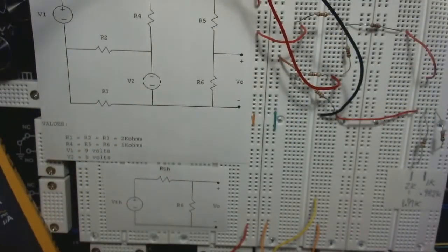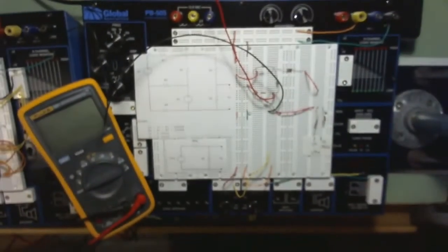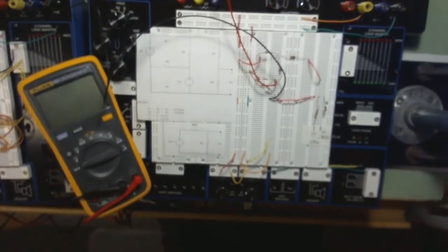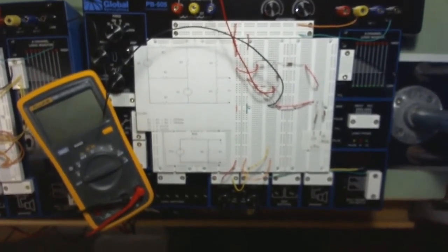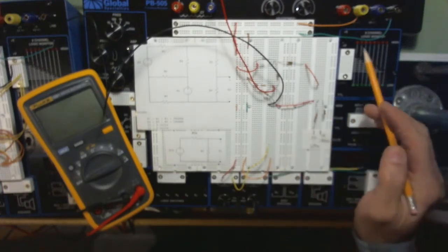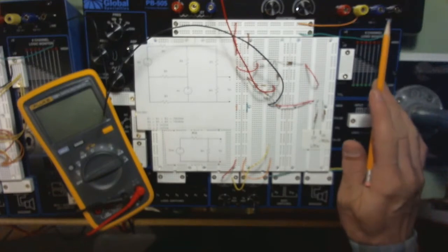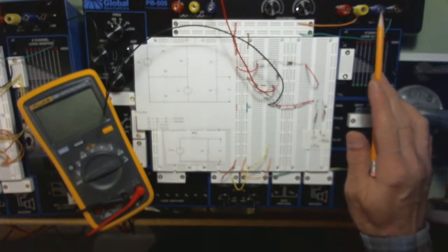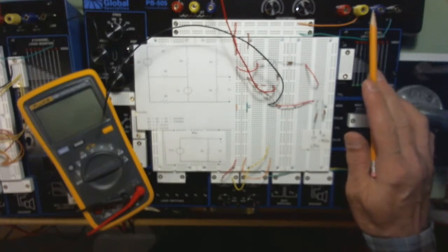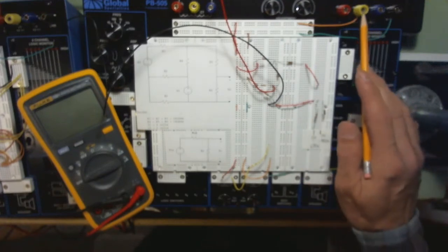I'll set this out of the way here, and I'm going to move the camera right here. It's probably going to be a little far away to really see everything, but I wanted to give you a little better idea of what's going on. Again, my trainer has a ground here. That's a ground lug. It's black, so it's a little hard to see on the black background. And then it's got a minus voltage, which we'll be using next time for our op-amp experiment. It's got a positive voltage, and that's what I'm going to tune to 9 volts. So this will be the 9 volts.